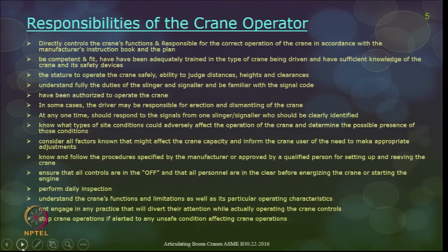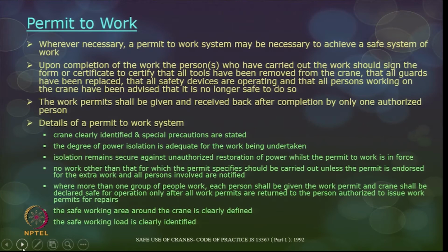So, when he has to get off, then he has to put the engine off and see to it that he has clear surroundings among the personnel, and only then he should do so, and stop the crane operation if alerted because of any of the unsafe conditions happening in the site.